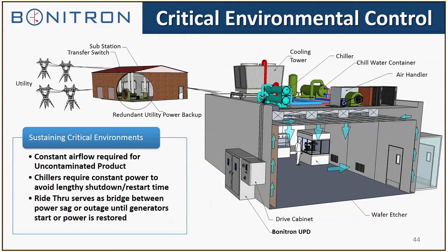In a clean room, this can cause a disruption of the fans or the air handlers, and the environment has to stay so pristine that, for example, in a wafer clean room, they will cross-section a human hair, and about 1/10 of that is a particulate that they're looking for on the filters as corrupting the air, to where they would just trash everything in the clean room, meaning it's been corrupted. You can't have anything get into the wafer manufacturing, or it will cause problems with the chips when they package them later on. That's the air handlers and the filters that actually keep the environment of the clean room pristine.